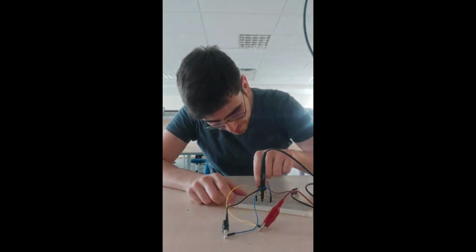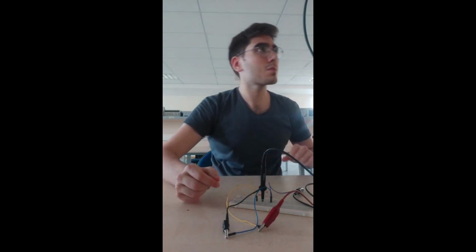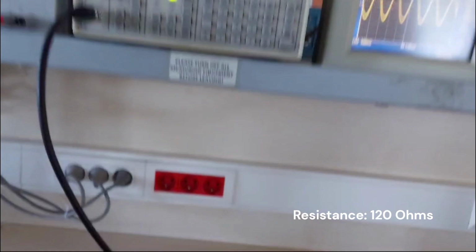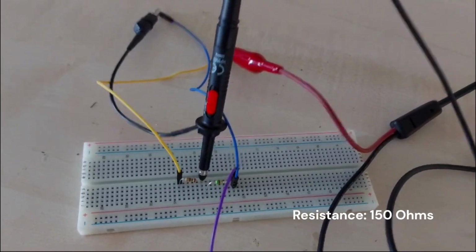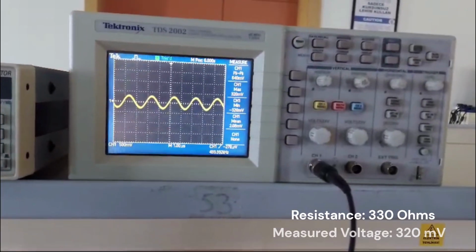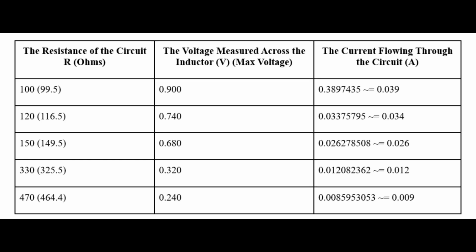For each of my measurements, I simply removed the resistor on the breadboard and replaced it with another one. For 100 ohms, the measured voltage was 900 millivolts. For 120 ohms, it was 740 millivolts. For 150 ohms, 680 millivolts. Next, for the 330 ohms resistor, I measured 320 millivolts. And finally, for the 470 ohms resistor, the oscilloscope showed 240 millivolts.